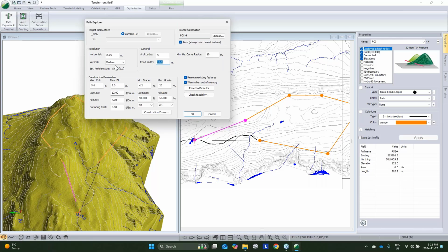this. Now we're going to have a much smaller prism than we normally would with a road. And the big one here that's going to make this take a little longer than what we'd expect with a road is reducing our resolution. So with the trail, as introduced, we can avoid little obstacles and kind of thread the needle through obstacles. So we're going to reduce our resolution down to make sure we're capturing something that works well with our horizontal radius and also captures those little details that we can make adjustments for easier with a trail.